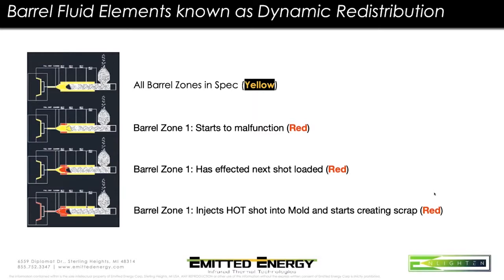It's the same thing if I was looking for an area on your mold. Well, the mold is getting hot. Where is it getting hot? Well, on this line right in through here. Oh, that's my water line number 3 over through here. And you take it out and you look, you blow through and you say, holy Moses, I'm not getting any flow through here. It's all gotten backed up. Or I had a diversion plug that slipped and now it's not rerouting, it's actually blocked off the water. It can pick this up, actually specifically where that particular area is.